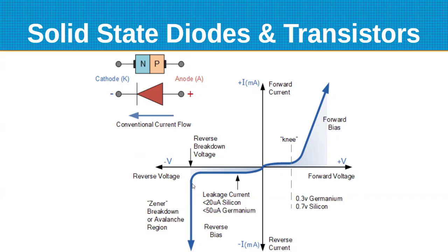And it's very precise. They can actually manufacture diodes, and we'll call them Zener diodes, where they control where this breakover point is to less than a percent. And that's used a lot for a voltage reference or in power supplies where you want some sort of known voltage. You just add a resistor to it, reverse bias it, and you'll get that Zener voltage between the diode and the resistor.